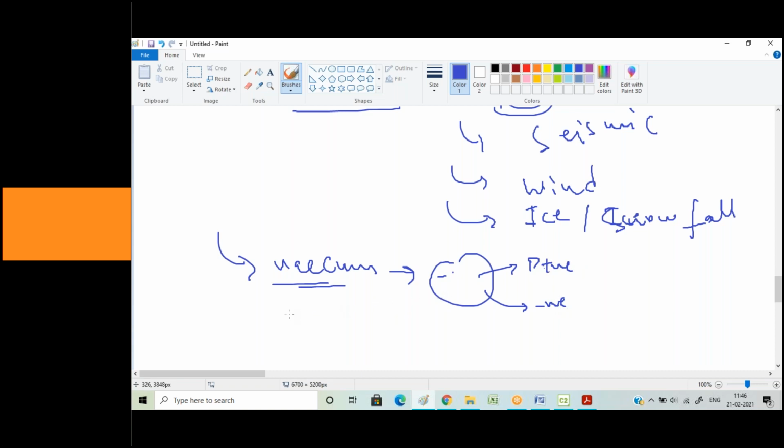Same goes with the temperature also. In case your line is susceptible to snowfall, or you're not giving any steam tracing in the line, or your fluid tends to change temperature and fall below a certain range, you can again make two different cases for temperature also, two design cases basically. Okay, so this is this.